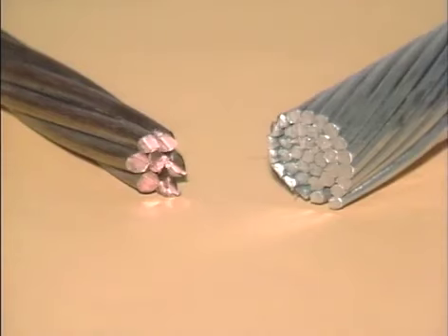But as I pointed out earlier, resistance is determined by the material the conductor is made of and the size of the conductor as well as its length. So let's look at conductor materials and then conductor sizes and see how they influence conductor resistance. Depending on the material used in the construction of a transmission line, its conductivity varies. Now, conductivity is the ease with which a substance allows current to flow. The greater the conductivity of a material, the less its resistance to current flow. In transmission and distribution, there are two materials commonly used in the construction of conductors. They are copper and aluminum.